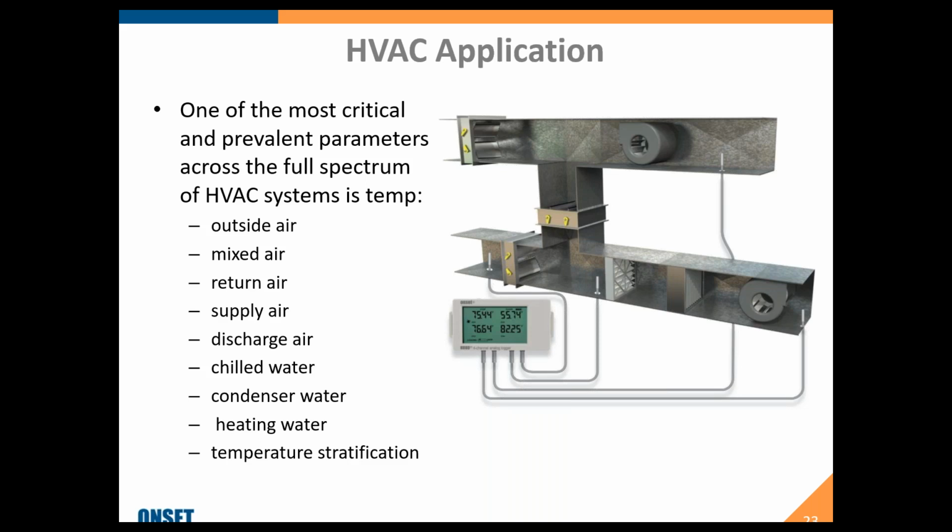Maybe they'll have one of our UX90s with a WattNode kilowatt hour transducer and some CTs to get a really better idea of the kWh draw. But for this one, it's showing you here where you have your mixed air, your return air, your supply air, just the flexibility with that particular logger.